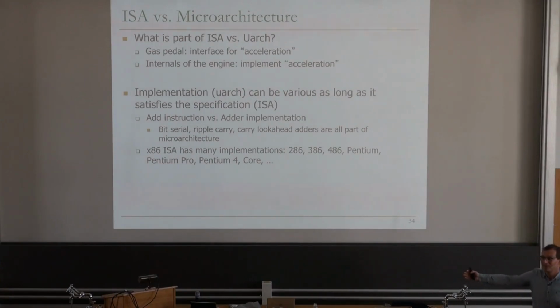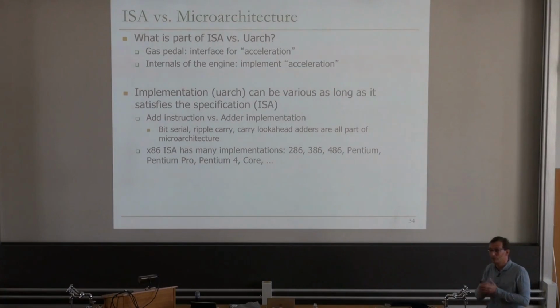The trade-off is different now, right? It's very energy efficient probably for that particular bitwise addition. It's very area efficient, but the latency is long. But it may make sense to implement something like this if you're doing a lot of additions, right? If you're doing millions and millions of additions, but you don't care about the latency of each addition that much, 32 cycles, who cares, right?